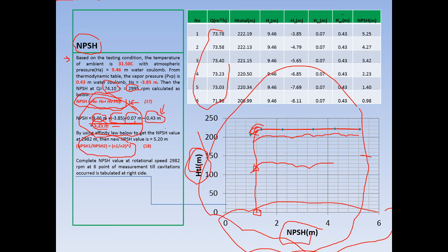So you have to compare this data. So usually, as a rule of thumb, NPSH available should be bigger than NPSH required, if not, it's dangerous. So it means let's say you put NPSH, for this case, you put NPSH available around, let's say, 6 meters.